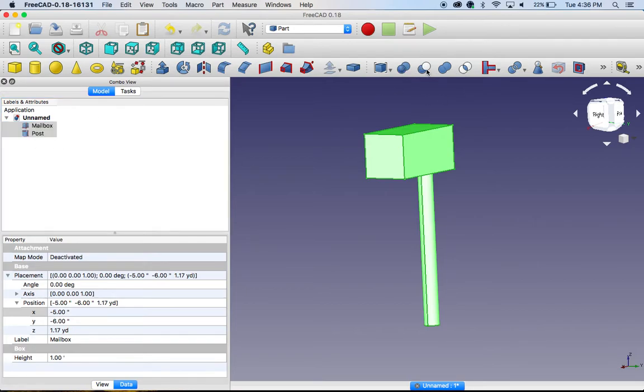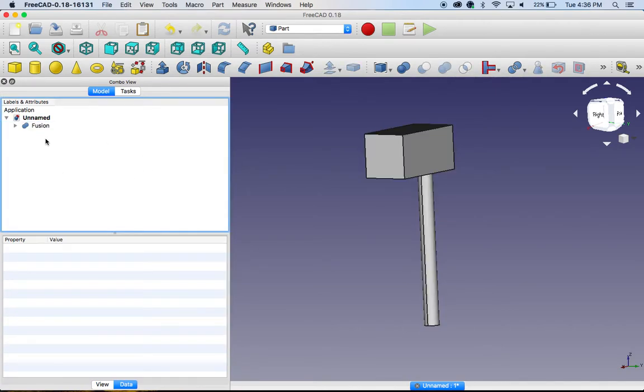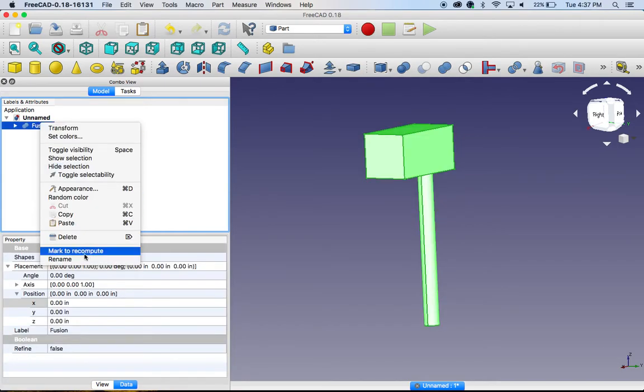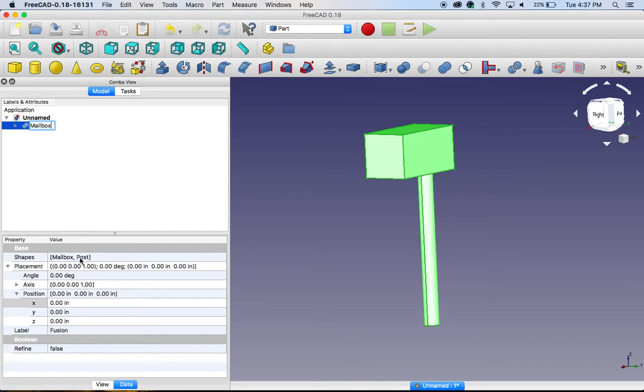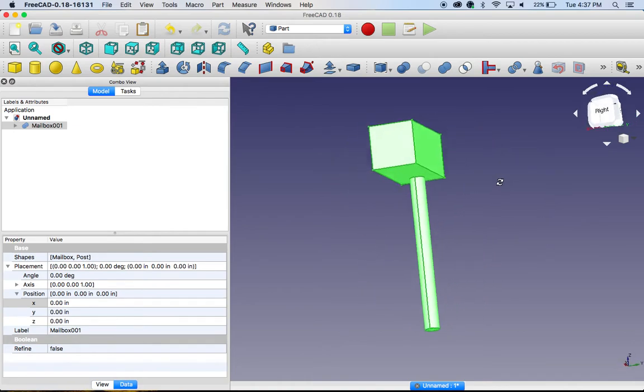And then you go, instead of where you used cutout before, you want to use the one next to it, which if you kind of mouse over says make a union or merge the shapes. So if I click that, in this case they're calling it Diffusion now, I now have one object, which is those two pieces combined together. So I'm going to rename this my mailbox because now I have one fused piece. So this entire thing is now just one object. It's no longer two objects.